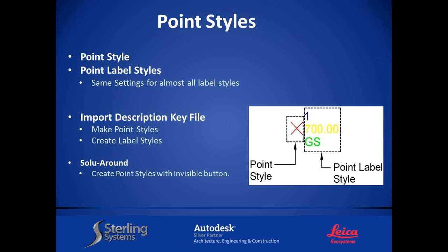And that label style is fundamentally exactly the same. Once you learn the setting, you can utilize this for all the other styles all the way through in developing that. So we're going to build one from scratch. Yes, it's going to be a little bit boring, but pay attention to this part because it will be used for the rest of the template that you build for all of your content. I guess real quick, again, hopefully keep those two differently. Point style is a symbol, the label style is the information next to it.